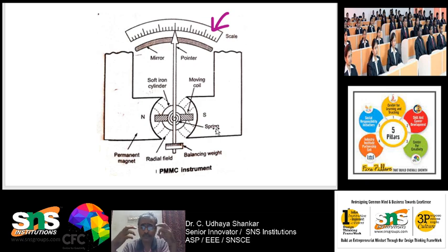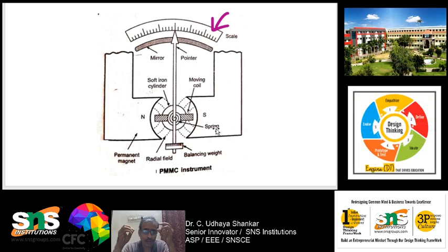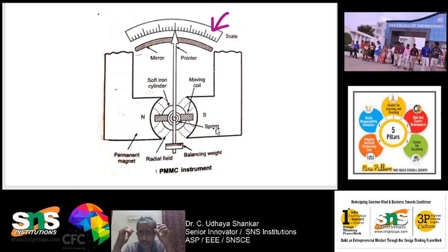For example, when the PMMC instrument is used for nearly 5 to 6 years, the permanent magnet will become slightly weaker due to aging, and because of which the reading may be quite erroneous. Okay, this is one type of error. The permanent magnet will weaken due to aging. As well, for high temperature, this permanent magnet will not work efficiently. This is one more problem.